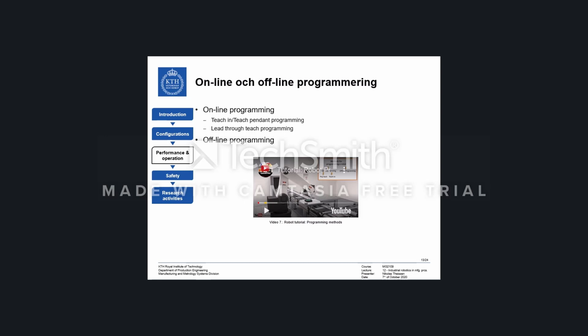As I said before, simplification is going to be a huge driver for the increased adaptation of industrial manipulators, and topics that are being researched in order to reduce the complexity associated with robot programming are to make CAD data available, in order to reference the CAD data to minimize the effort required by the operator, using different complementary modalities, meaning that communication between the human and the robot can be based on speech and gesture.